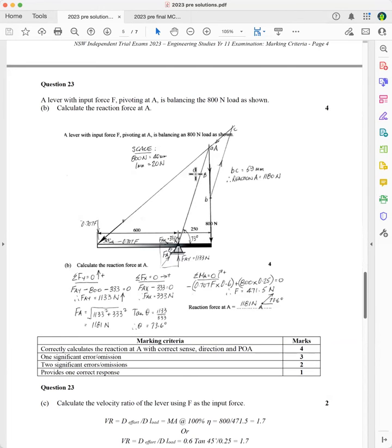And then the next force will be CA, and it's got to go through point A, so you just extend that on. All the forces are depicted by the arrow here, so it goes down, and they all have to go in the same general direction. So you can see that this force, the reaction force, is going up to the right.